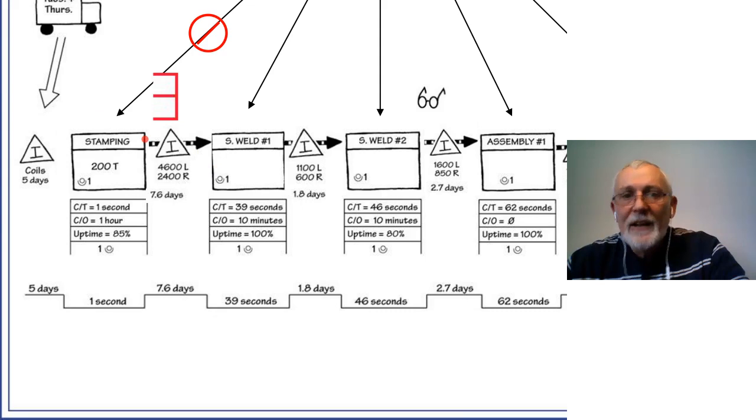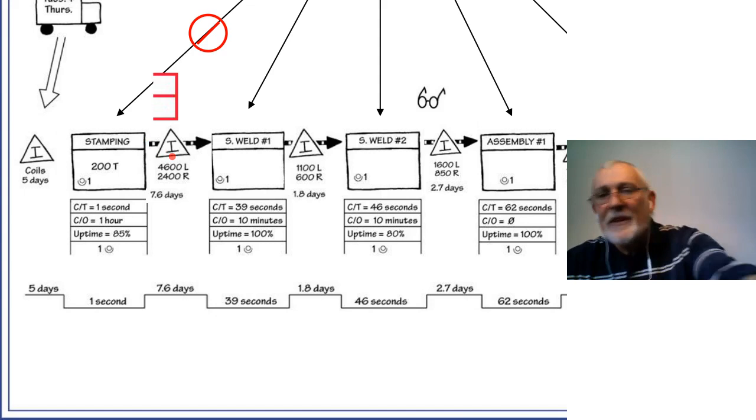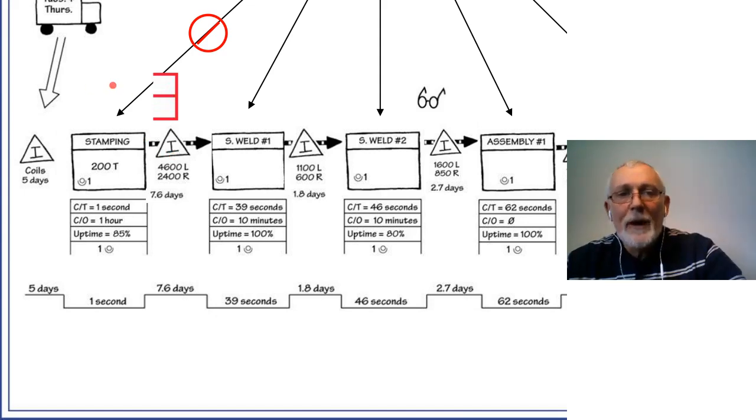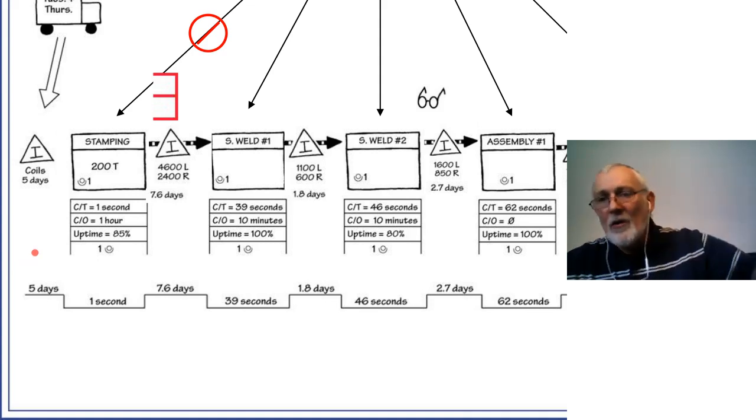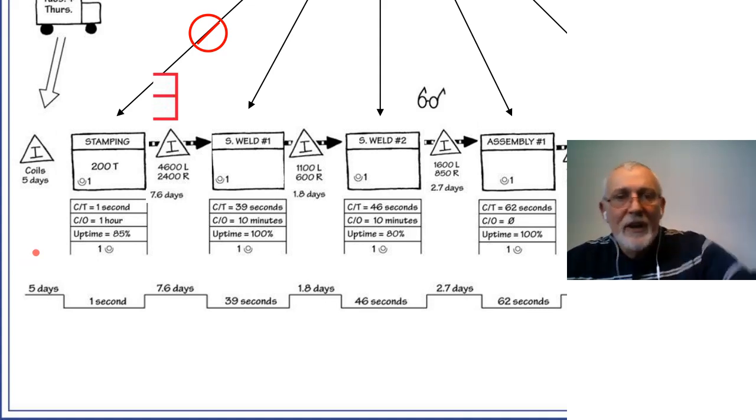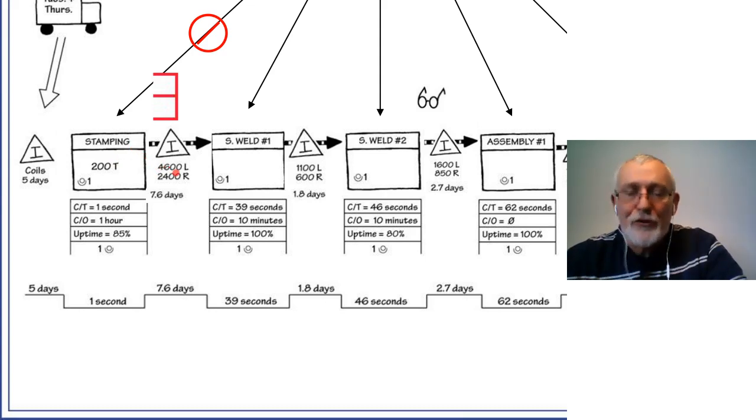So ideally, if you could visualize what we've got with the stamping machine is we have a supermarket beside it to feed this particular line. We'll have another supermarket potentially above it, and another supermarket out here, and another supermarket off here, all of which are servicing the different product lines that this particular machine manufactures parts for. Okay, so the concept is it's a shared service or a shared machine. It provides multiple products and multiple product production lines. And what we're doing is we're putting a store there, a supermarket shelf, and we'll pull from it and put a trigger system in place to drive the replenishment as the materials are used.